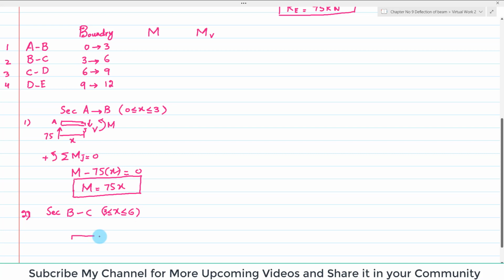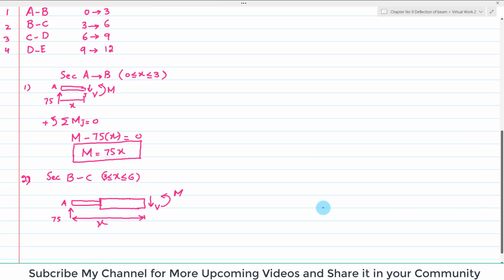So you can see there is a smaller beam and then there is a beam with the larger thickness. So if you cut the beam, there will be a shear force and moment. And the same at point A, there is a 75 kilonewton and this distance is X. So again, this is the same scenario as the above. So its equation of moment will be, again when you solve it, it will give you moment is equal to 75X.